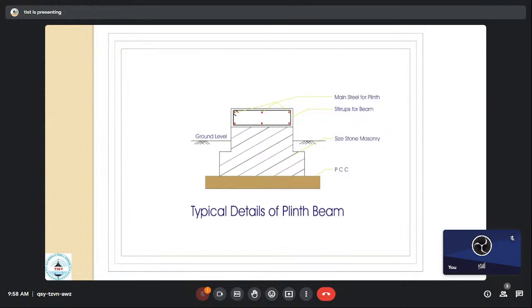If there is a plinth beam over there, the effect of the seismic activity passing on to the superstructure will be lesser. So there is a binding type. If you take a bunch of broomsticks and provide a knot over there, that acts as a firm attachment. Am I correct or not? Similar to that, for the entire structure, this plinth beam has a different name also. Colloquially they will say something like belt. Am I correct or not? Belt, colloquially they say so. That is also there.